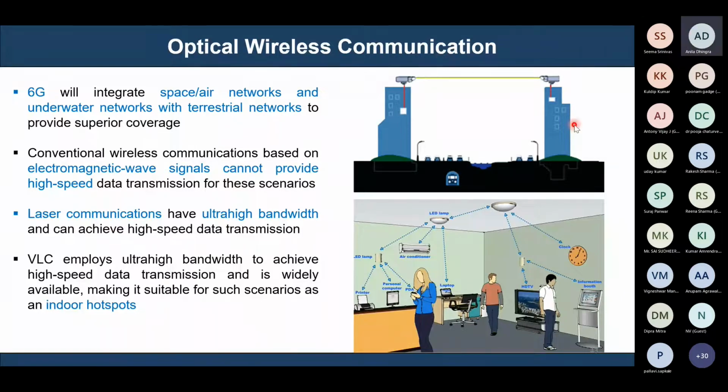Now the next segment is the VLC segment. People are looking at LED bulbs, which are very good. They use 400 terahertz to 800 terahertz, and the advantage is that they can support a very high data rate over a low range within the building, or where there is not much sunlight outside, right? Daylight noise is limiting outside of the building. So within the building visible light communication works very nicely, but not outside of the building.